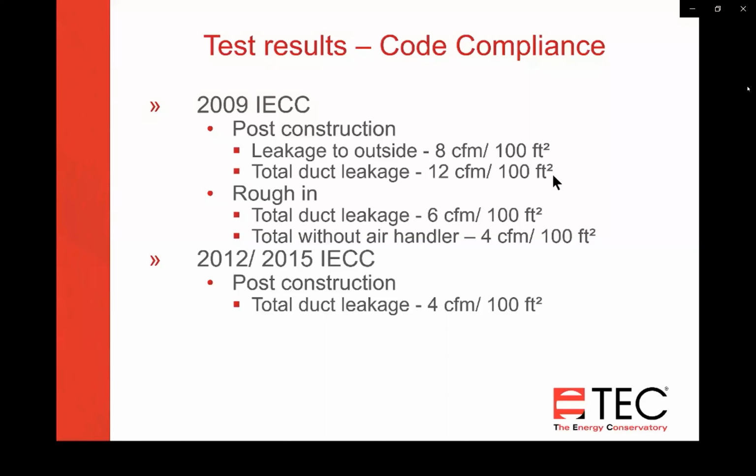So they needed 4 CFM of total duct leakage. Now duct leakage, the outside isn't part of the equation. You have to do a total duct leakage test. You only have to do the test if you have ductwork outside the envelope, outside the heated boundary of the house. But you do need to do a total duct leakage test.